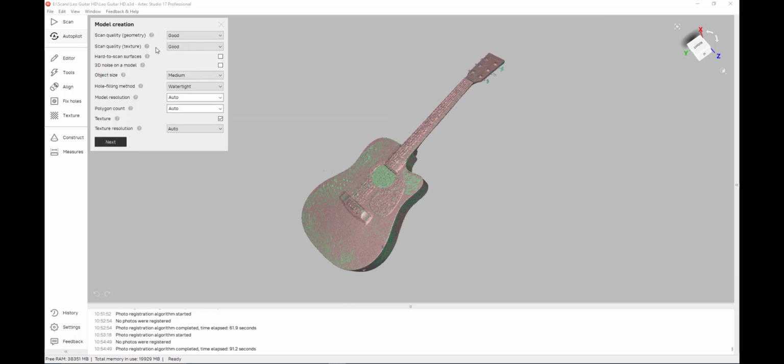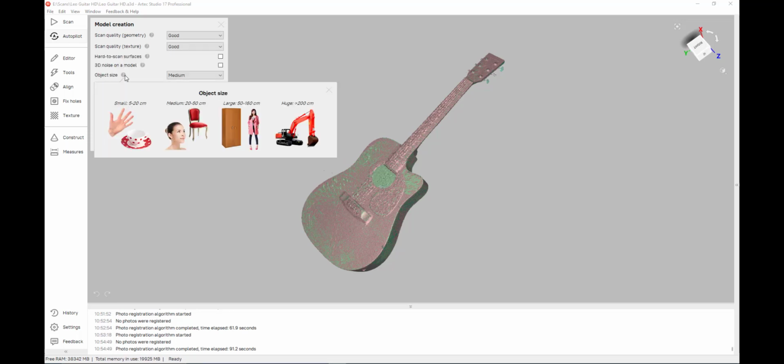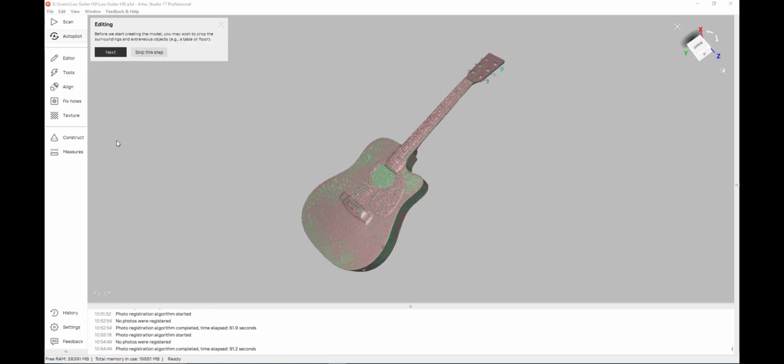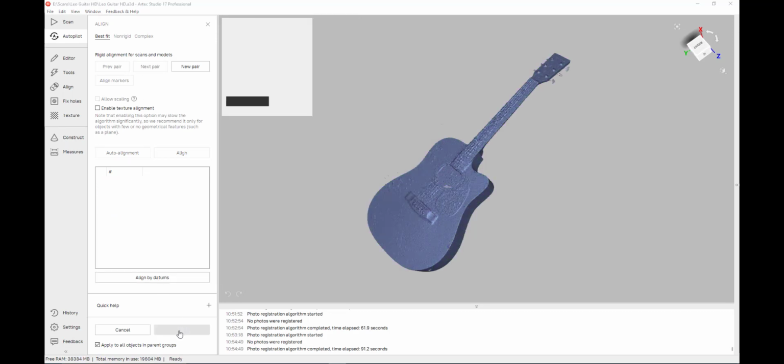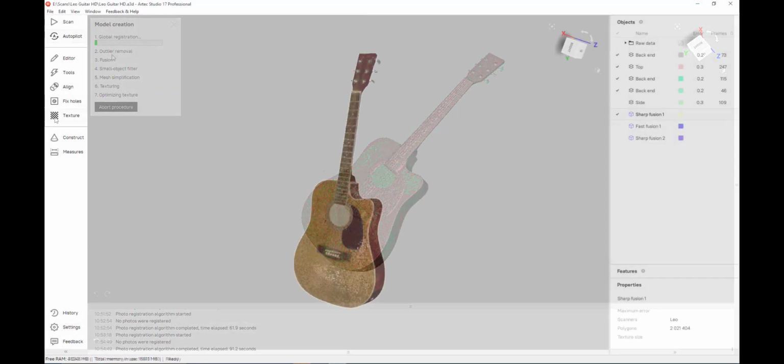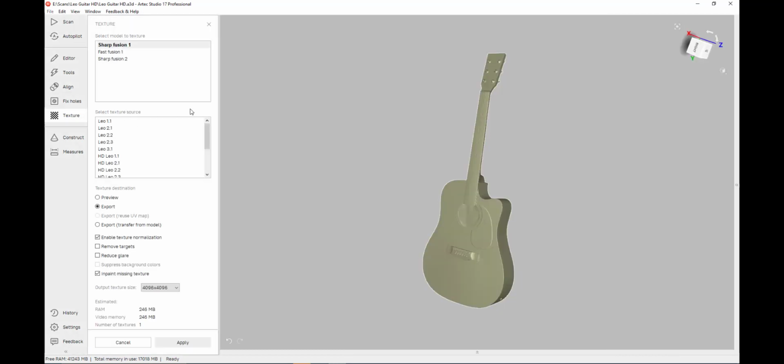It will first ask if you want to clean and align your scan data, then run a global registration, outlier removal, and fusion steps based on the questions asked in the earlier prompts. This is handy for new users who aren't sure what to choose yet for the manual settings when processing scan data. There's still more to show off, however, inside of Artec Studio. So far we've just created a mesh, but we can extract more information and add color to this mesh.